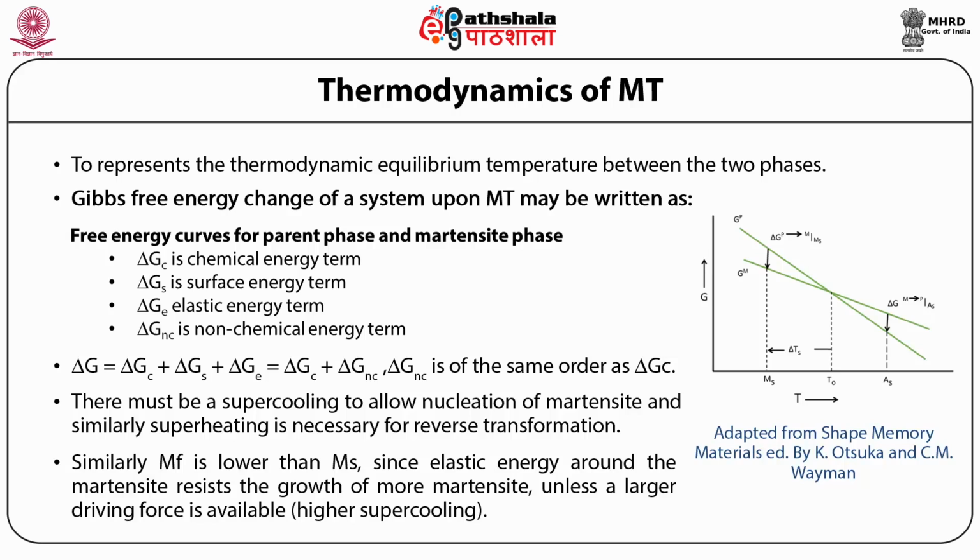Hence, the transformation will go to completion at even further supercooling, and hence MF is less than MS. Thus, the transformation is only temperature dependent and not time dependent.